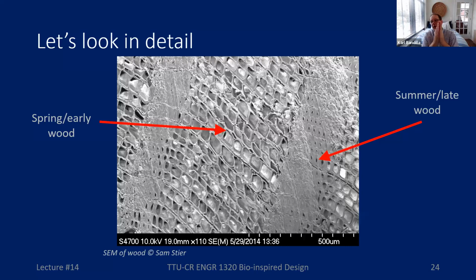If it were only the hardwood, it would break off, because if a car runs into it, it needs to move a little bit and then come back. If it's very rigid, it's going to break. But if it's a little bit flexible, it can withstand that. If it were only the soft material, it would just flop over all the time. So you have to have these two, and the combination is this great composite material.